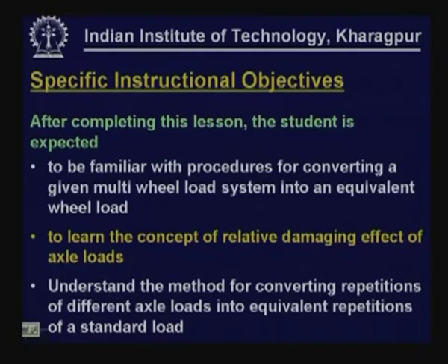We will also learn the concept of the relative damaging effect of axle loads, and using this concept, how different numbers of repetitions of different magnitudes of loads can be converted into an equivalent number of a standard load.